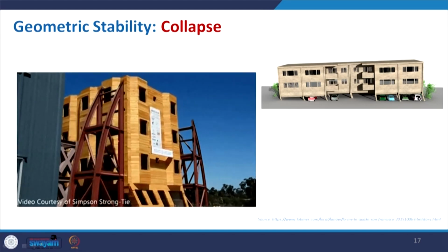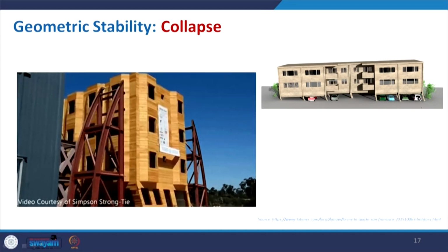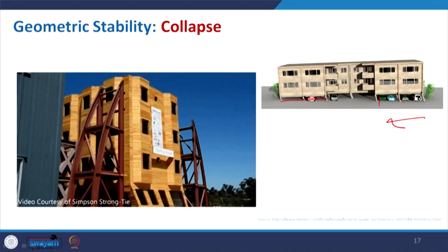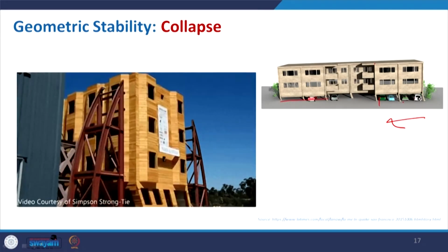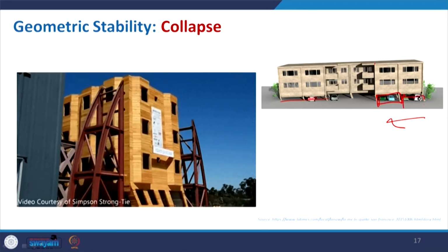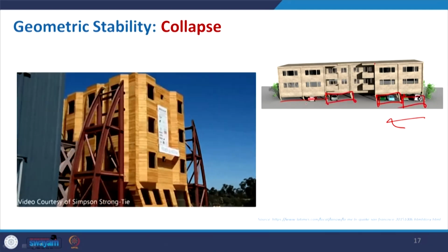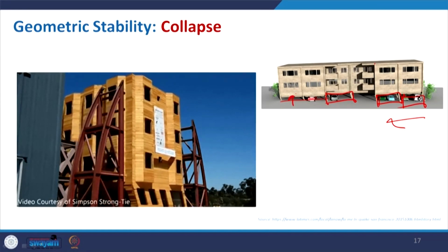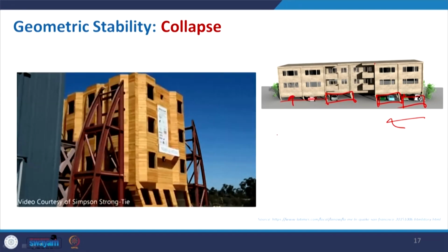So, this is a testing model, and actually during an earthquake this is the case. Again, what I mentioned, heavy mass on top of the columns is very dangerous. So, for an earthquake prone area, you have to go with some good structural arrangement like a shear wall, or else you do not go for a soft story, otherwise due to the motion this will happen.